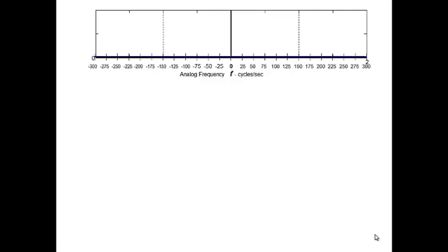And what is that picture? Well, the Fourier transform of this is an impulse shifted to this frequency f0, the frequency that I had in here, 100, with a 2e to the minus j 5 pi over 6 complex scale factor, which, if you want to use a shorthand notation, is 2 angled at minus 5 pi over 6. Right? So that just means that my impulse has a complex weight.